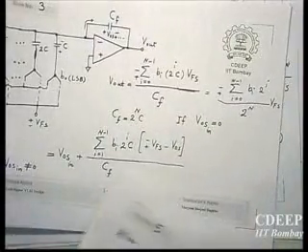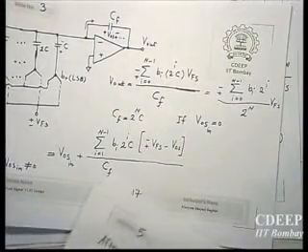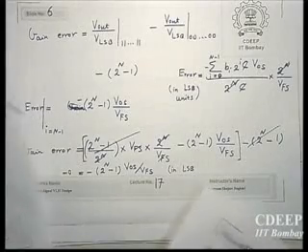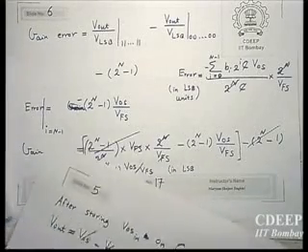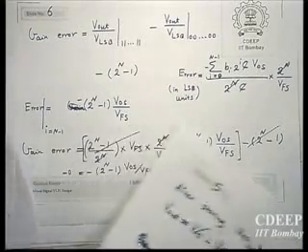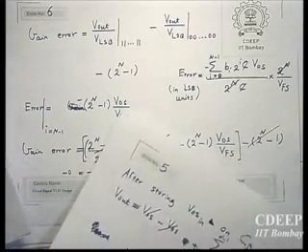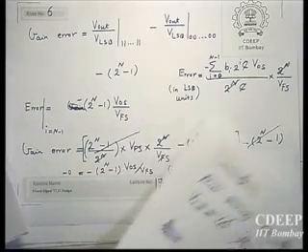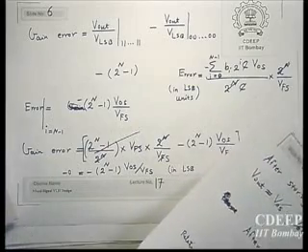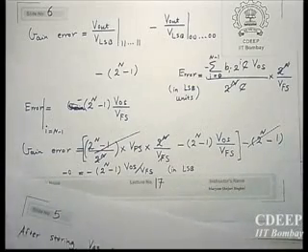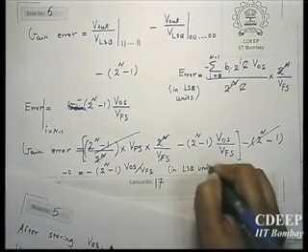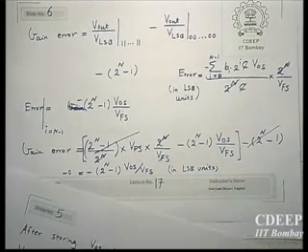Offset error eventually is this summation offset upon C, and this will be 2 to the power n. And now for this particular i equal to n minus 1, it will be 2 to the power n minus 1 V offset. Okay, here I have multiplied, so it is in LSB units. Fine. So this is gain error.